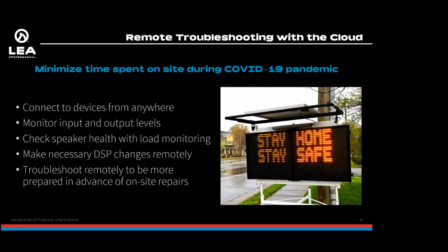Minimizing your on-site time as a technician troubleshooting something, you can connect to the devices from anywhere you've got an internet connection, monitor your input-output levels, check the speaker health with load monitoring, and make any necessary DSP changes, all remotely. Being able to troubleshoot your speakers or amplifiers from off-site can really help minimize time on site, and maybe even prevent a trip where it's not needed.